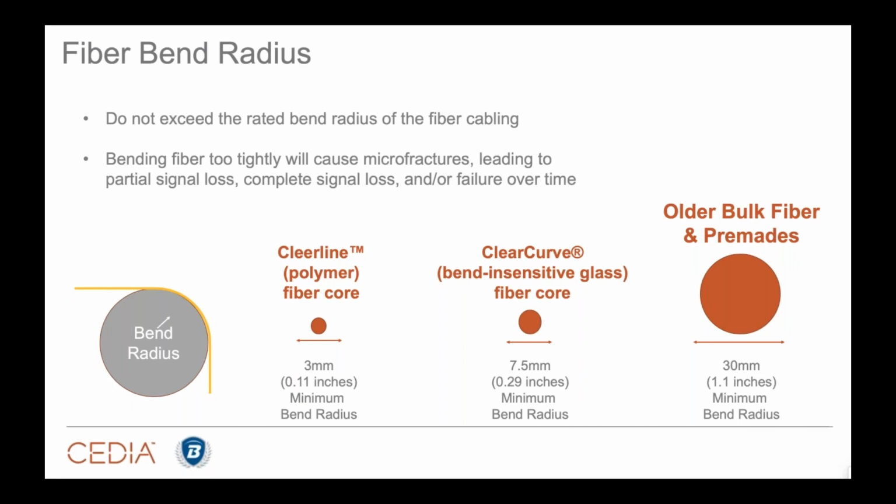You've got to be careful with it, because the worst thing that can happen isn't that you break the cable. If that happens, you know it's broken. The worst thing that can happen is you damage the cable, because what tends to happen with fiber is if you damage it, get a crack in it, that crack gradually spreads over time. It will degrade, fall apart, and it takes a long time for that to happen. And your customer will see their performance fall apart. It's incredibly hard to troubleshoot. Handle those cables carefully.